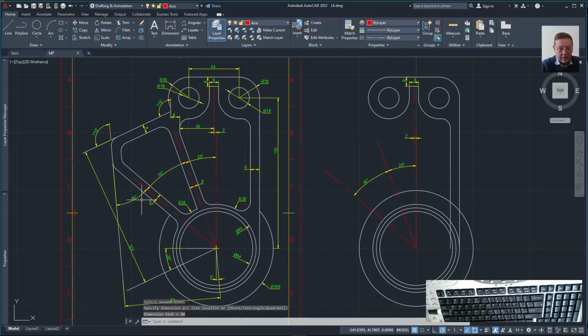Okay, until now it's quite okay. Going back to the layer 0, I will make an offset of 4 millimeters of this line here, this line here, and of course, I will choose these lastly realized segments and I will put them on the layer 0. Of course, making after that the necessary trimming.